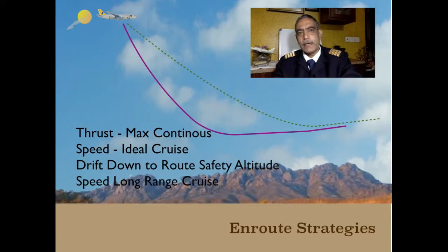Why? Let's appreciate if you have had an engine failure, the first aim is to quickly land in a place to secure the aircraft and passengers, and so on. In most cases, this best L by D or the best climb speed which we are talking about is at a low end of the range of speeds which are possible. It's at a very low speed. So it is going to take much longer to cover the distance at the best lift by drag speed. However, the rate of descent would be so low as to clear all the terrain which is possible. So let's discuss these two scenarios.